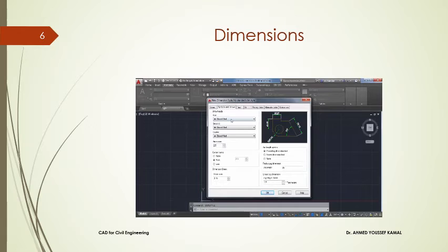So here we have some arrows. So now we have close fill as the default arrow. Let's change it to some other arrow type. In this case I'm selecting this right angle arrow. Now the arrow type has been changed, and you'll also observe that the second arrow type is changed. But if you change the second arrow style, it will not change the first arrow style. So in order to change both, just select the first arrow style and both will be changed. Let's click and change it to right angle arrow style.